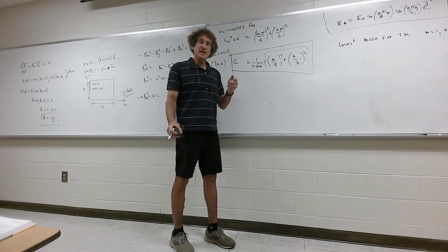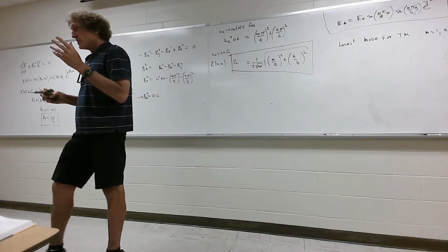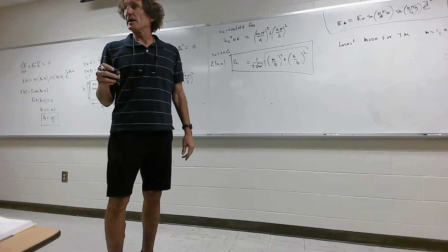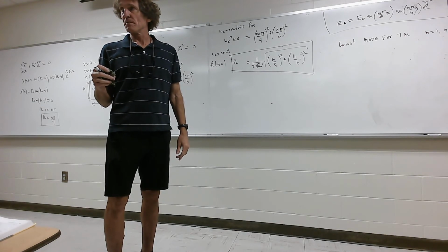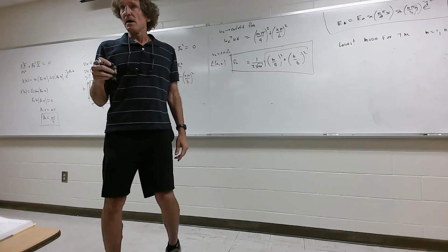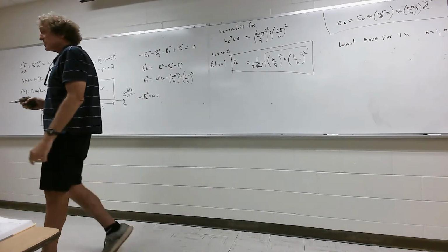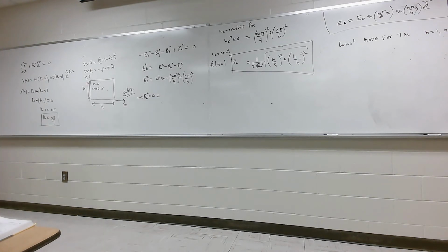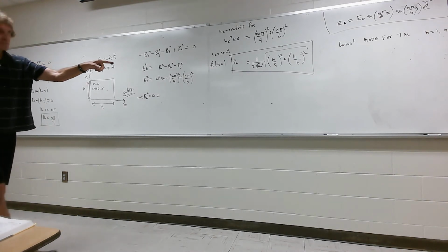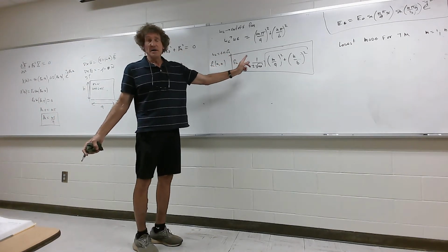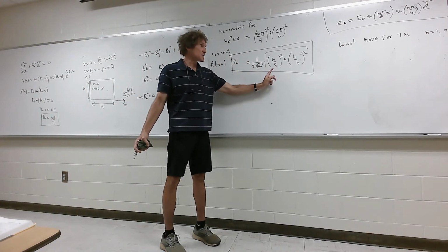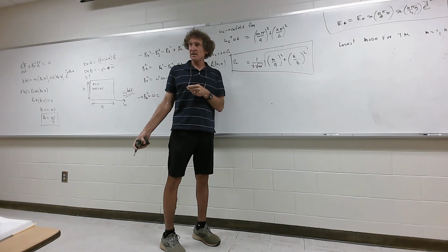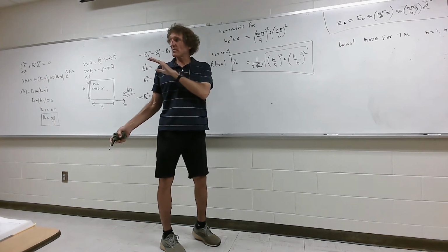And you'll see when we do the TE mode, the lowest frequency is a 1-0. What are the m and n? Integer values that indicate the mode number. Is that just a given for the waveguide? Well, m and n are just integers. The thing that determines the actual frequencies are the dimensions a and b and the values of mu and epsilon inside the guide. Now let me give you some perspective on what they mean when they say a mode number.